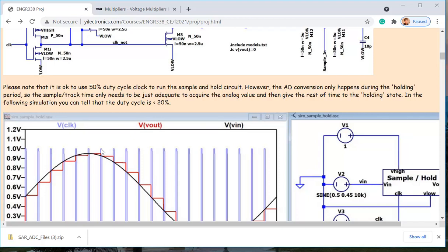You have to make the sample and hold clock yourself. How many clock sources may you have when you are interfacing your digital system with any ADCs or any other off-the-shelf ICs? Usually there's only one.